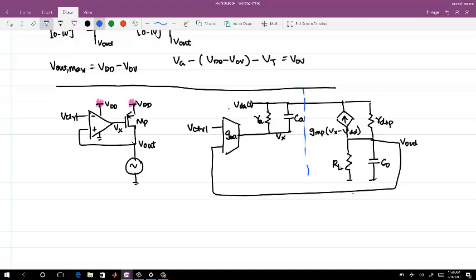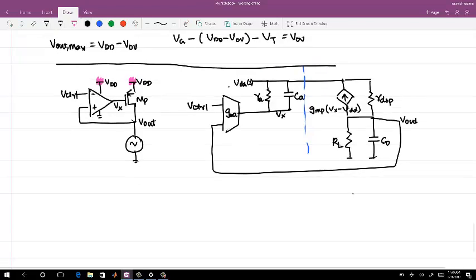The interesting thing is if you do the analysis and you do not consider the noise on this resistance RO of the op amp, you will find a different noise and you will see some different characteristics. So while doing the analysis, you cannot neglect that the noise is directly coming to the output resistance also. Got that point, right?